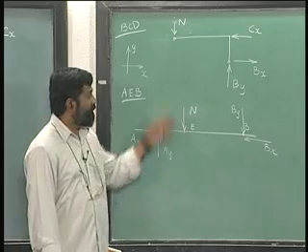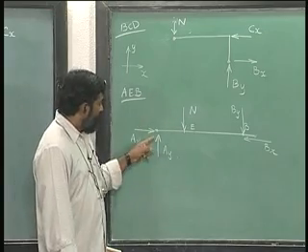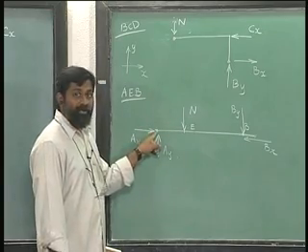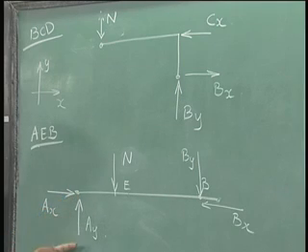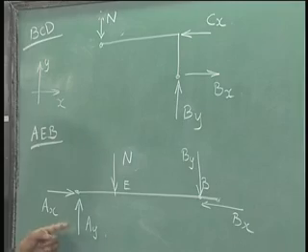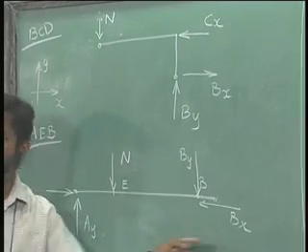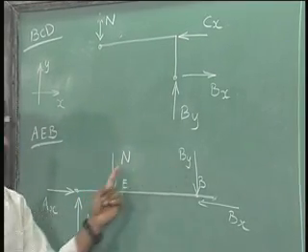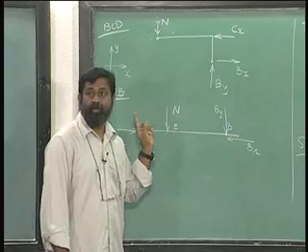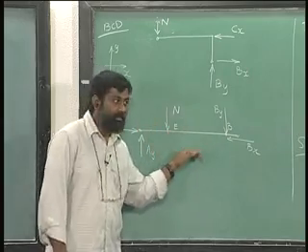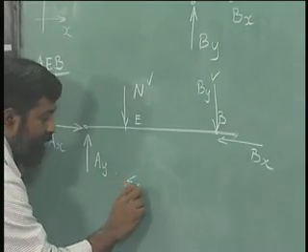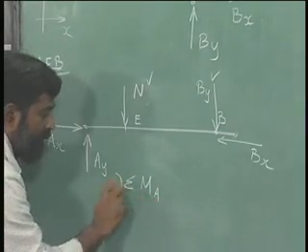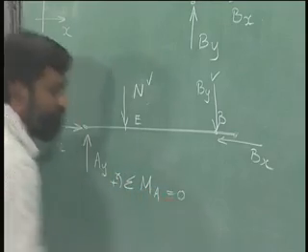Okay, how do we solve for the other unknowns? We already saw 5 here, 5 there. If I take moment about this point, what all unknowns can I avoid? I can avoid Ax, Ay as well as Bx, which means I will have an equation that is in terms of N and By. Is that clear? So, N and By will take part if I have moment equal 0.